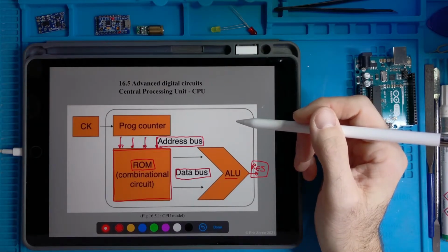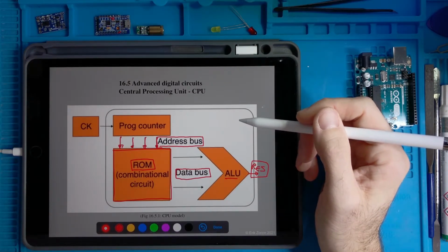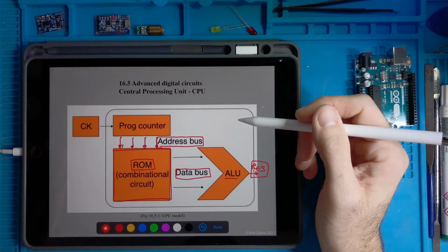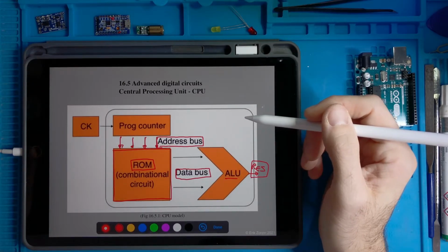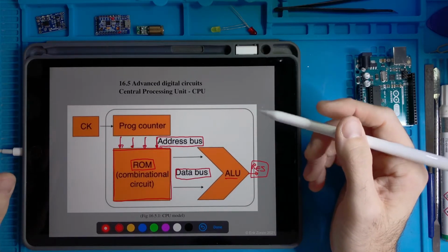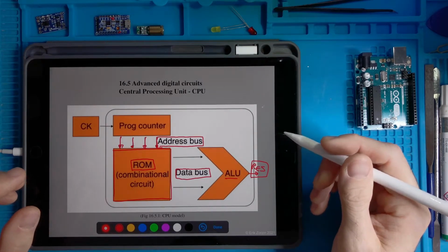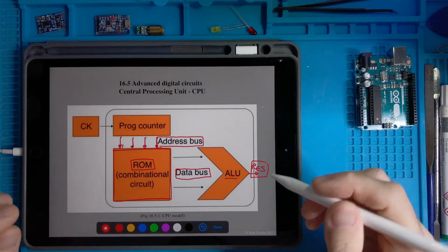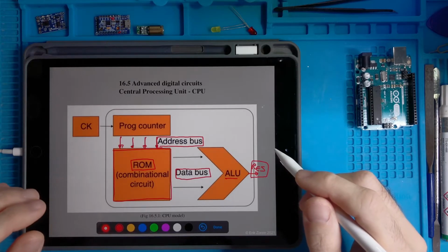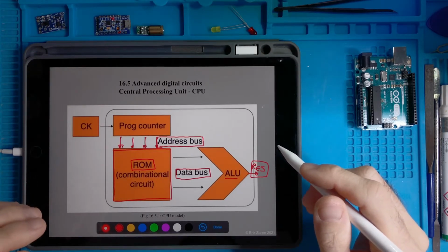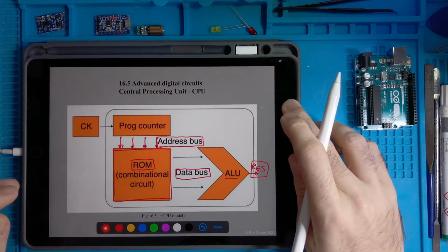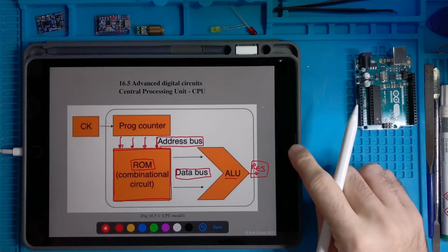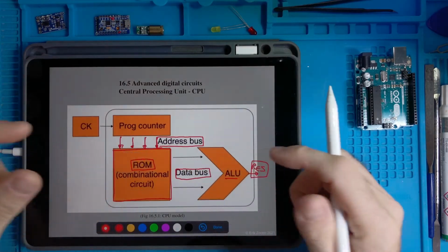Every bit of the RAM is a capacitor that you can charge, and then you read the value. If you want to set it to 0, you discharge it. If you want to set it to 1, you charge it. Those capacitors are implemented in the silicon chip directly, and they are very, very small and very integrated, so the RAM can be very big in a very small chip.